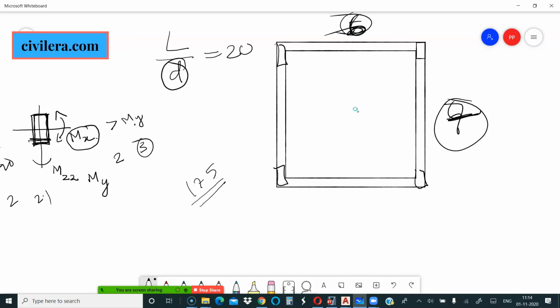Even with BE or MTech experience you should know that for a normal building, it is not great to have a slab thickness of more than 125 to 150. Having a very thick slab for such a small room is not a great thing. So you ideally would not want a slab thicker than 150. With a 6 meter span that is not possible, so you will give a beam.